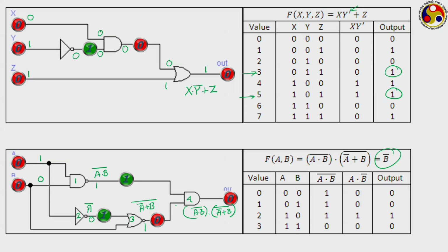So, this AND is receiving 1 from the lower side, this gate number 3, and another 1 from the NAND operation. So, this is a standard AND gate. So, we are getting 1 as the final output. So, for the 1 0 combination, this is the final output 1. This is the only case we are getting 1 in this particular scenario. All others lead to 0.